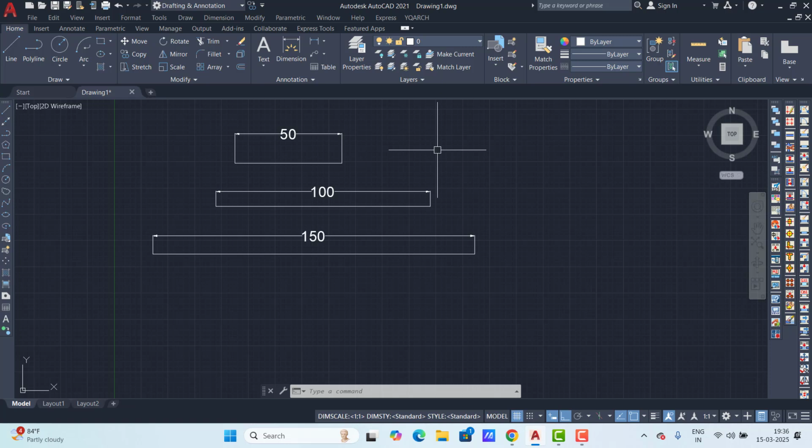Now you select here, and the total length increases by 15%. If you click again, this time it takes the current length and adds 15% of that. So if you use percentage, you have to click carefully, one time. For the second value, 115 multiplied by 15%, how much comes? This is how it goes. Press L, E, Enter just for the dimension, and check with the DI command.